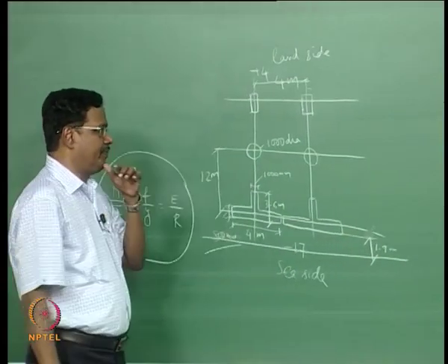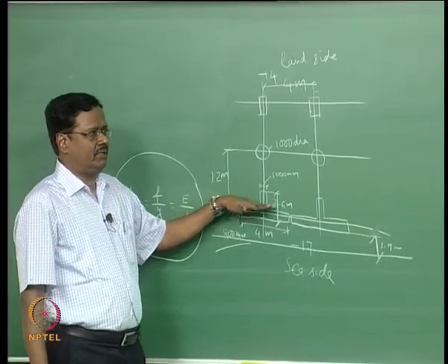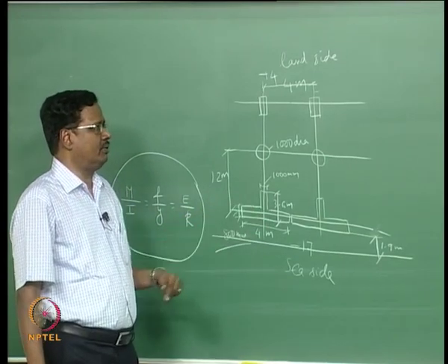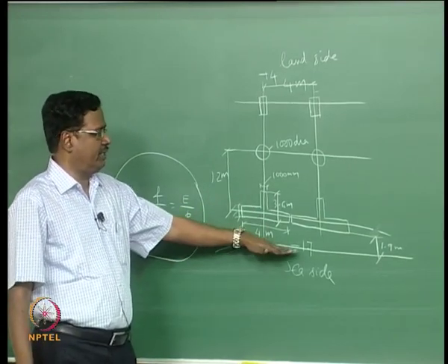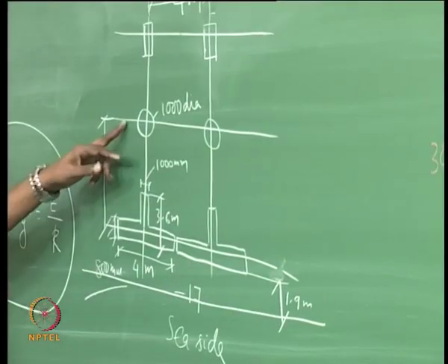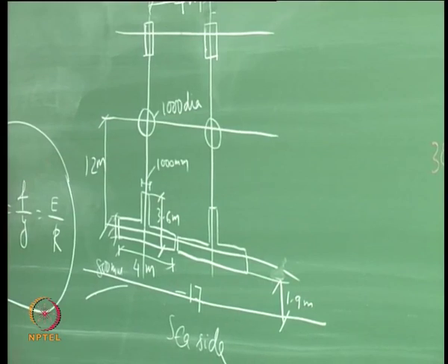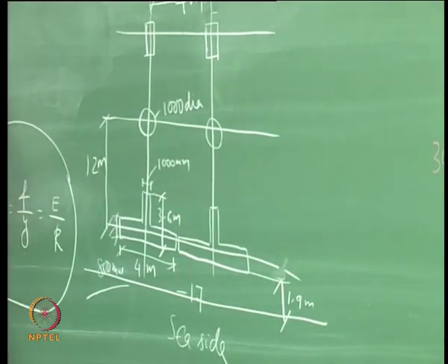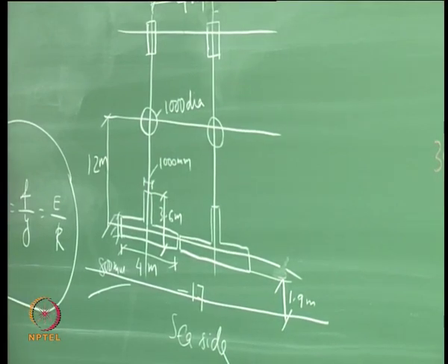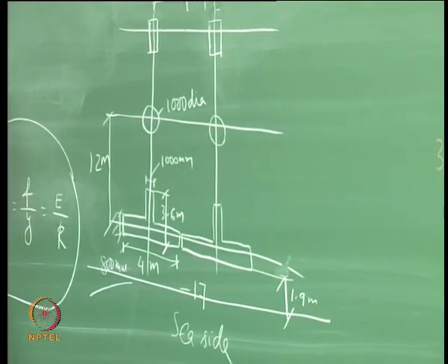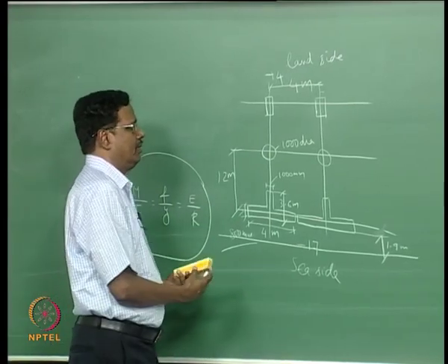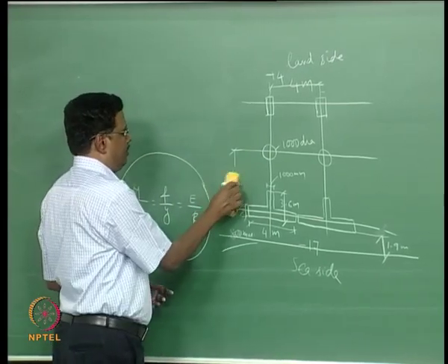We do not want the diaphragm wall on the face of the berth, because when the ship comes by, some tilting should not go and hit. So there is a fender beam here, then there is a fender, afterwards the wall is here. This diameter is 1000 dia, spaced at 4 meters center to center. Flange center is given as 9.4 meter.